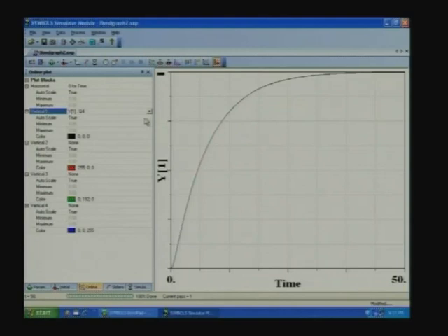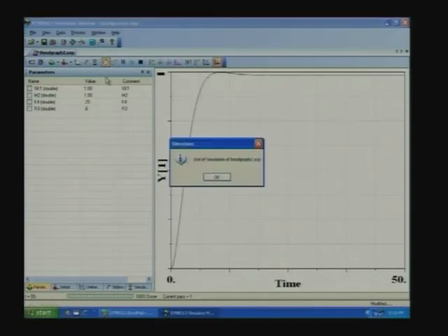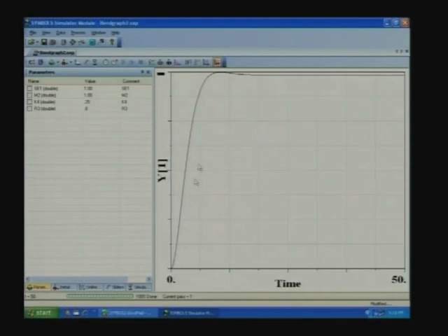So, if it is slightly underdamped, then what is the behavior? Slightly underdamped, I will make it say 0.8 maybe. 1 was the critical case, right? See, it has gone slightly above and then come back.